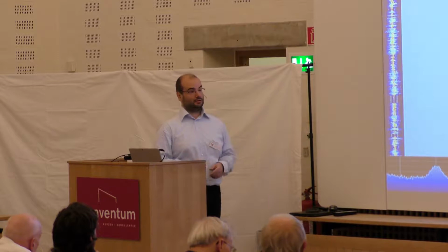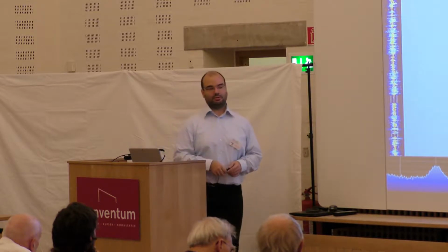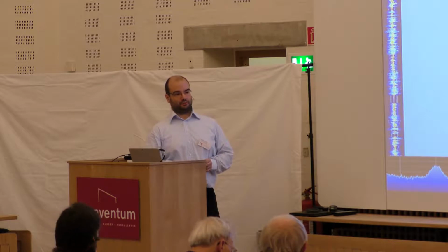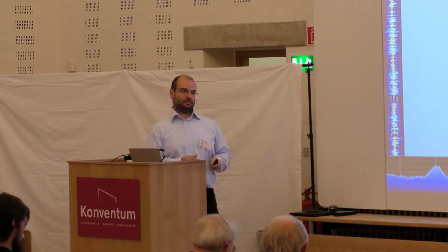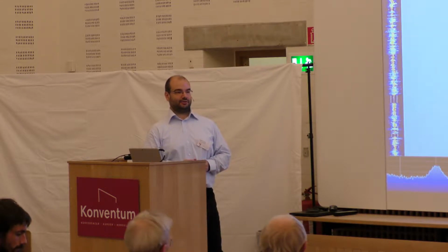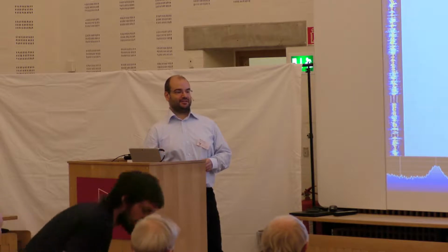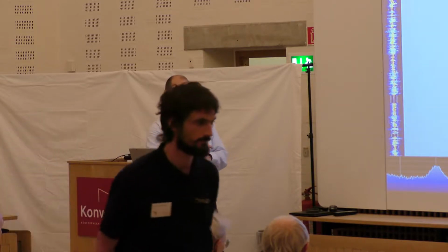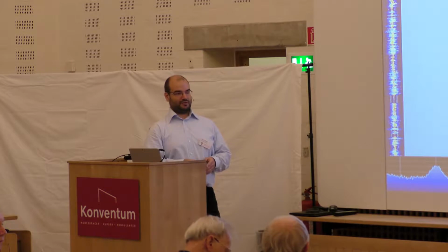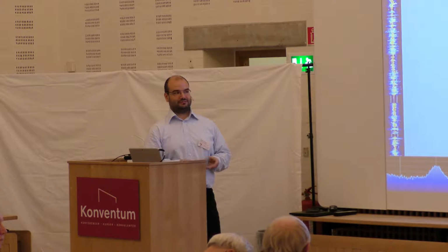Well, this device's lower bound is 24 megahertz, so it doesn't go down to that. However, there are projects. Maybe it's already possible to go down to 100 kilohertz in direct sampling mode, where the chip is connected directly to the antenna, bypassing the tuner altogether. So it might be possible to achieve these frequencies, and once achieved, I don't see any difficulty in doing something like this.